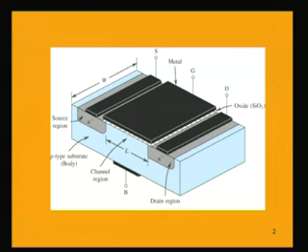there will be capacitances between the gate and the source, as well as the gate and the drain, as well as the gate and the body. So, we have three capacitances coming into existence because of the presence of this dielectric in between the gate and the substrate.